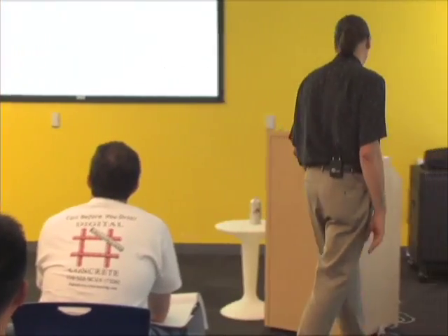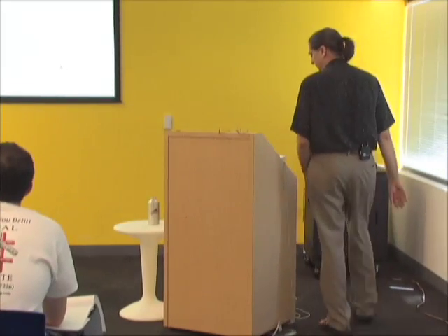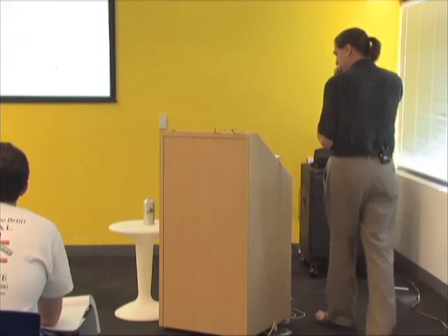But SketchUp's really good about changing layers. It's really great about deleting layers because, unlike other programs, when you delete a layer you can really delete the geometry on it, or you can convert it all back to 0 or to any other layer. Everybody understands that concept? Anybody not understand that? Because I'll show that later. I have to mess up my simple example to do it.